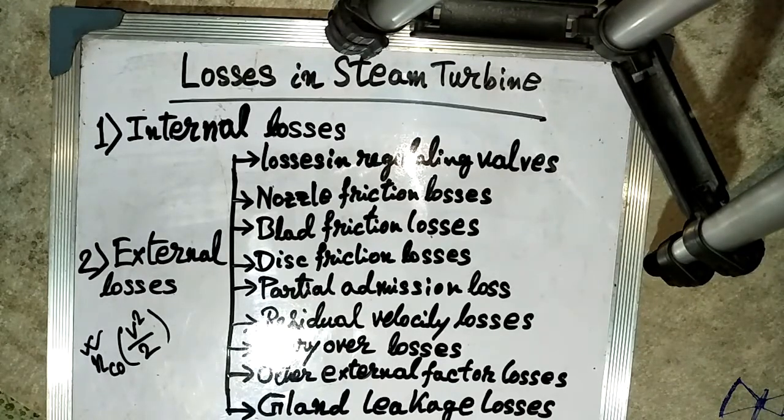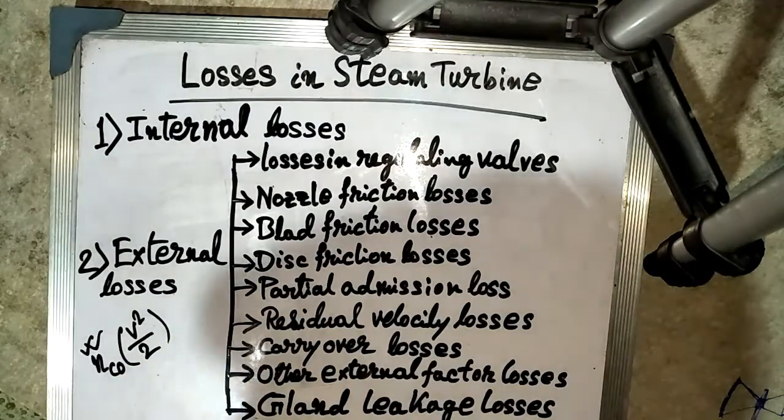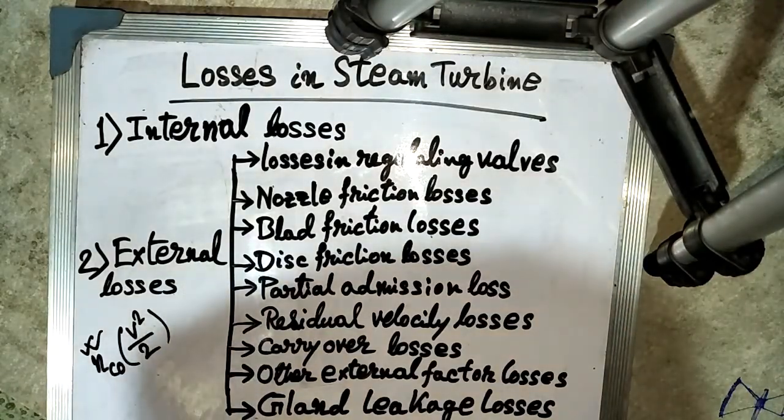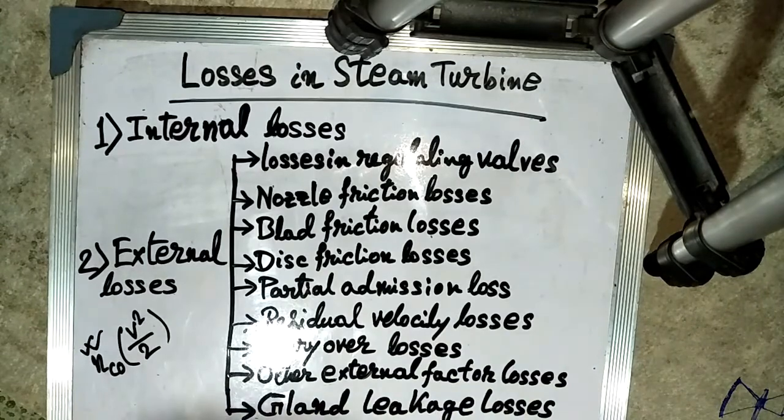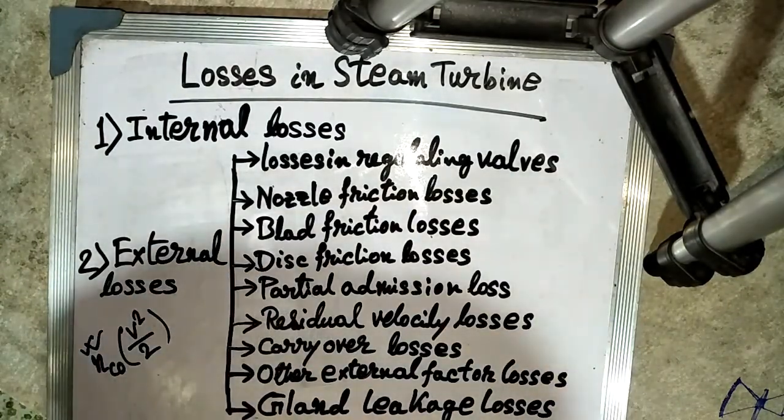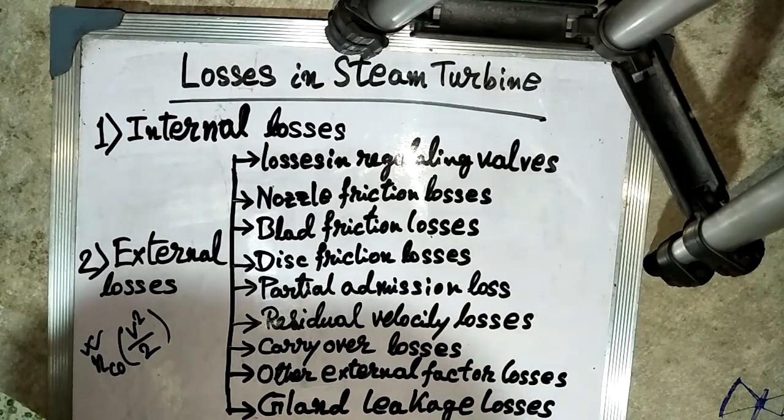In addition, there are some losses of energy due to the wetness of steam, where the water particles are dragged along with steam at the expense of some kinetic energy of steam. If the quality of steam is less than 0.88, erosion and also corrosion can take place.